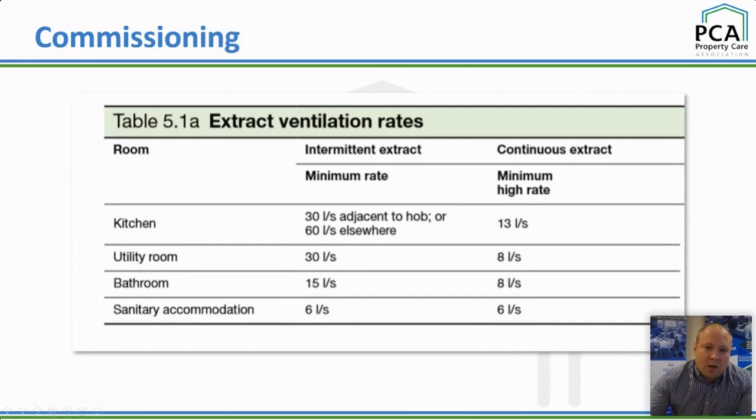And the one thing I haven't commented on yet, it should be reported to building control in advance. There's 3 exceptions to reporting to building control in advance. One is that you're a competent person through schemes. And I should probably say, it's not just an electrical competent person that they need to be.